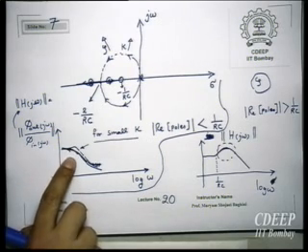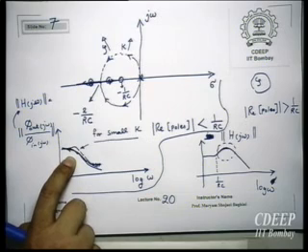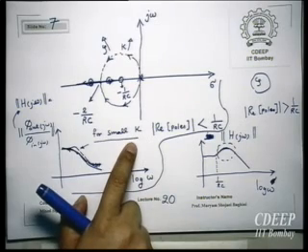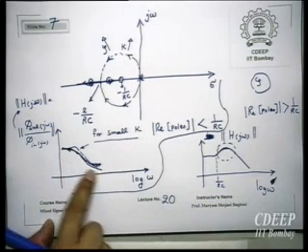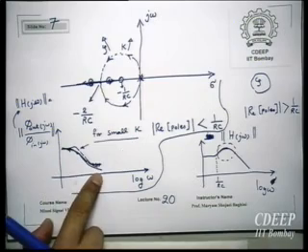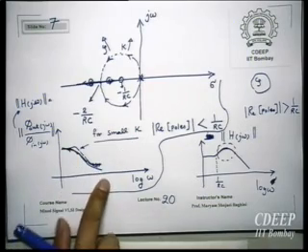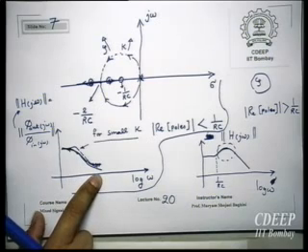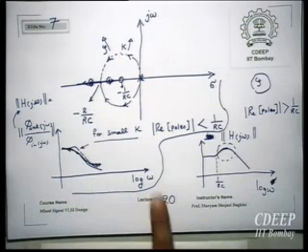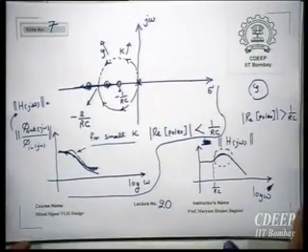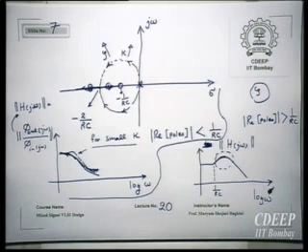Here, if you don't have as such a large peaking in the left part, when your loop gain is small, it's not very large, here you won't see any peaking. And with respect to jitter performance, you have a better design, but with respect to stability, you have to be careful. The reason is because, as I said, the stability itself is also a problem.